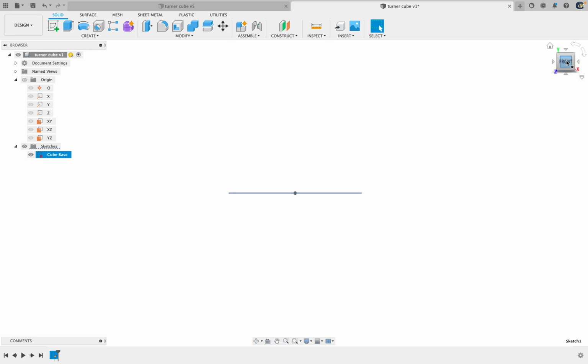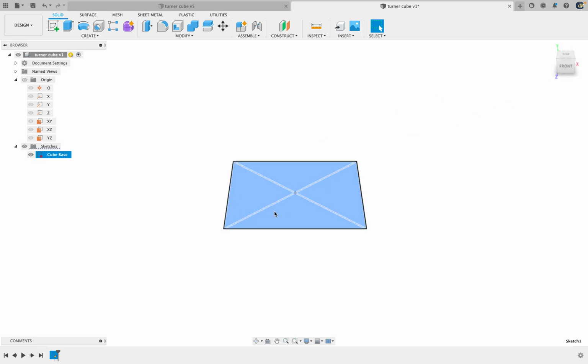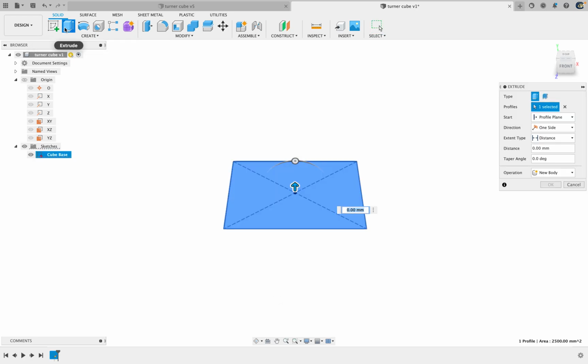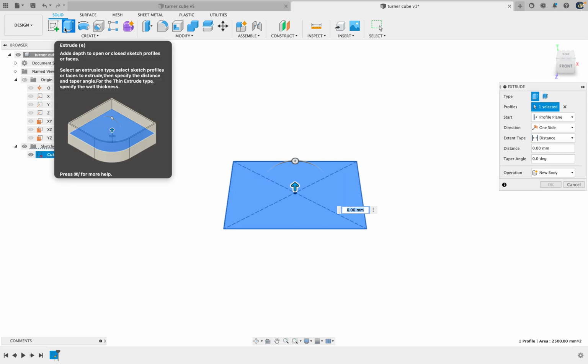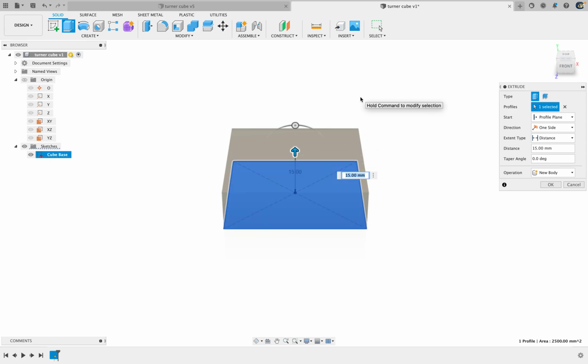And now let's 3Dify this. I'm also going to show you a new kind of extrusion here, because I want to keep the origin, this guy right here, exactly in the middle of my design for the entire time. So if I would, and I'll show you the wrong way first. So if I went and clicked extrude, now remember, this is the wrong way. Don't do what I'm doing right now. If I would extrude that up now, to make it a cube, we know it's 50 wide by 50 deep. That means I would need to make it 50 tall as well.